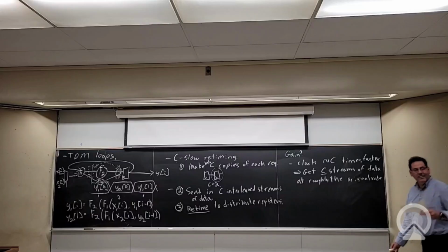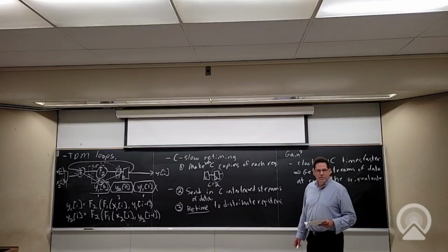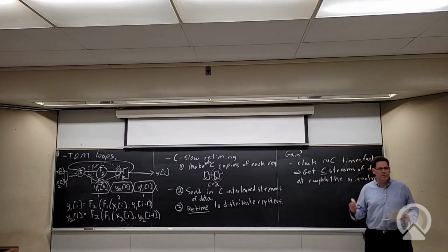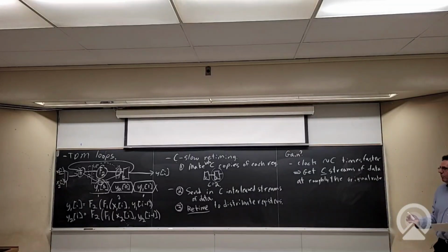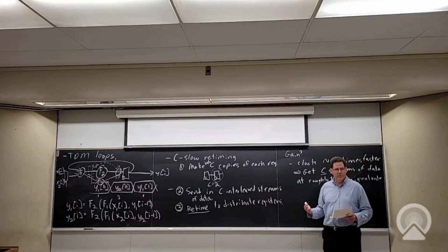So, yeah. The way you're describing C-slow retiming, it sounds like almost an algorithm that the CAD tools would do, but I'm assuming they don't do this because it's kind of disruptive to the... I've seen academic tools do it, right? So there are academic tools that will do this, where they're basically trying to research this kind of optimization. I don't know of a CAD tool that will automatically do it because they worry about breaking your functionality. Quartus in its timing optimization guide will actually tell you you might want to do this, but it doesn't do it for you.